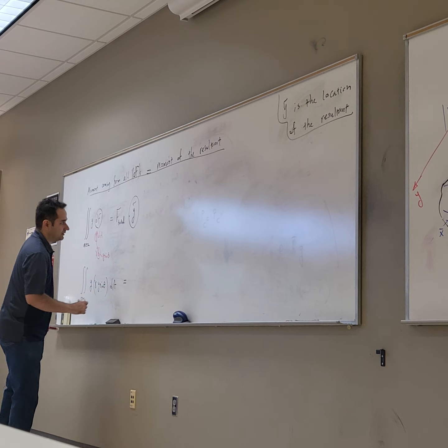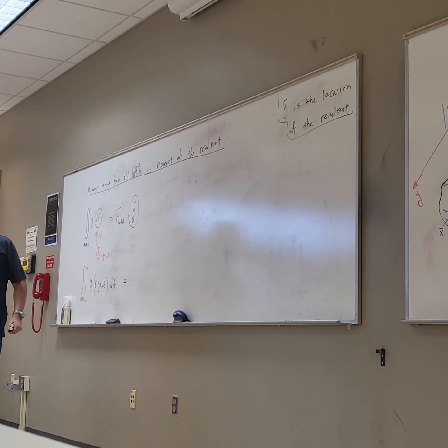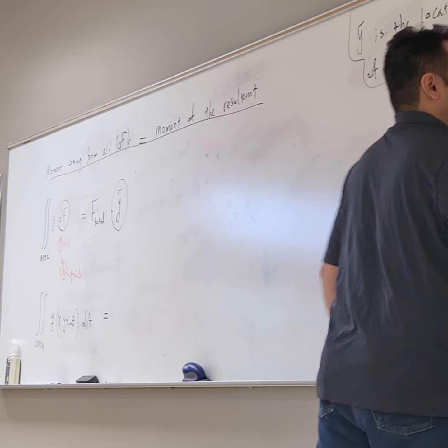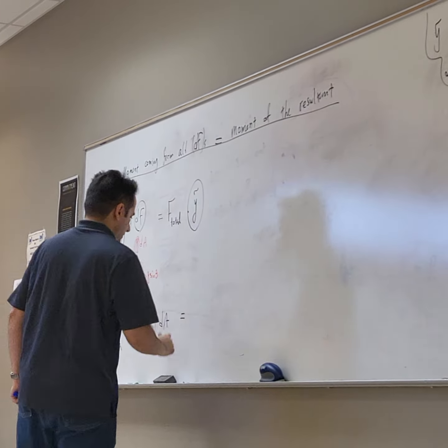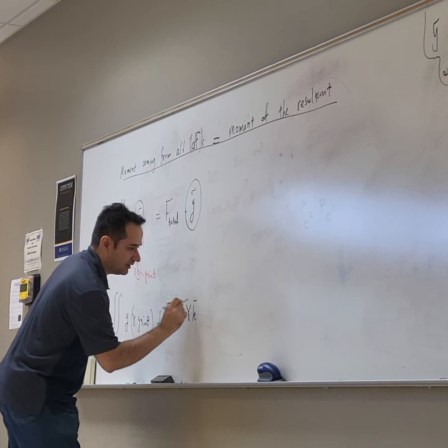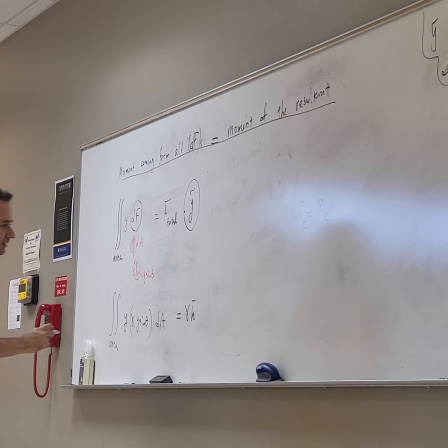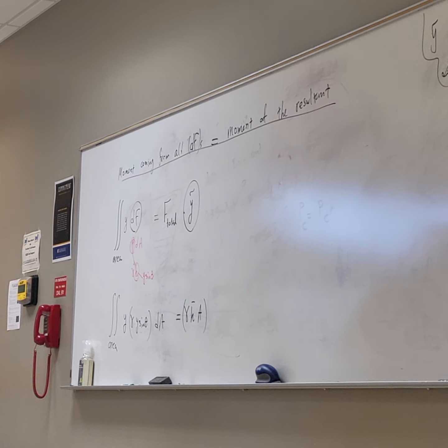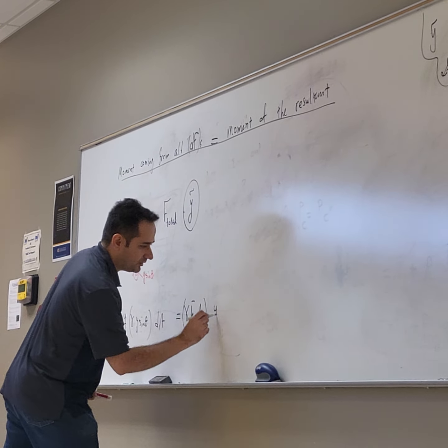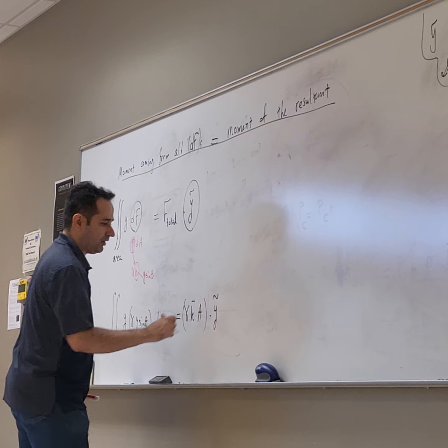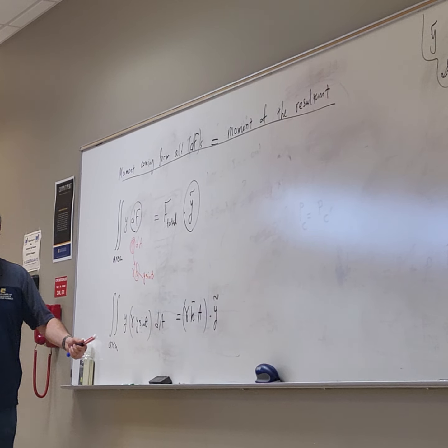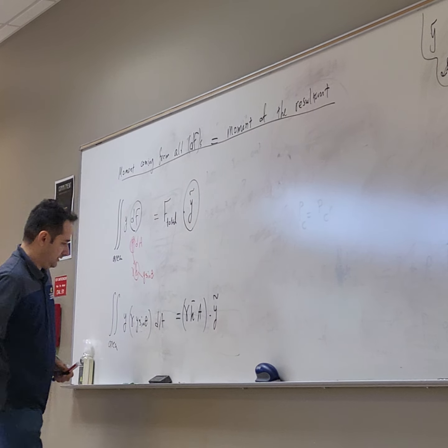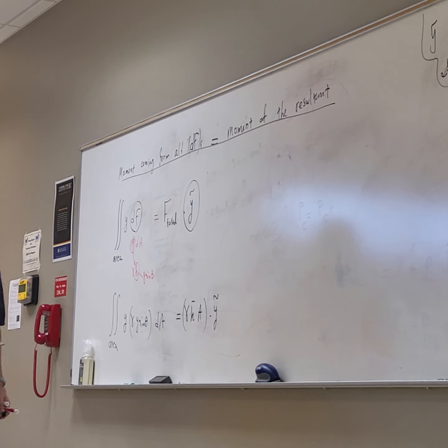The right hand side, what do we get? What was my F total? Its magnitude was gamma times h bar times A. That's your F total times y tilde. And I'm trying to solve for y tilde. So that means y tilde is equal to this guy, whatever it is, divided by that guy. So let's do that.